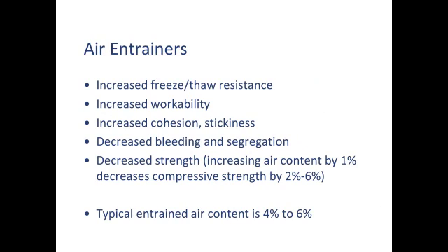Typically, the amount of air that you're targeting is 4 to 6%, sometimes a little bit higher than that, but generally 4 to 6%. So that's the total volume. So if you had a cubic meter of concrete, 6% of that cubic meter would be air, entrained air. If you're just making interior concrete and you're not doing entrained air, you're probably going to have about 3% trapped air, which is the big bubbles you tend to see that we deal with as pinholes, that are not effective as freeze-thaw resistance. So air entrainers are basically, they create microfoam inside your concrete.